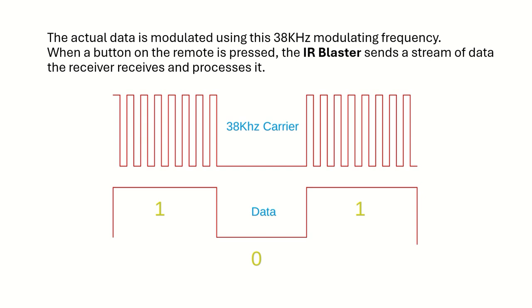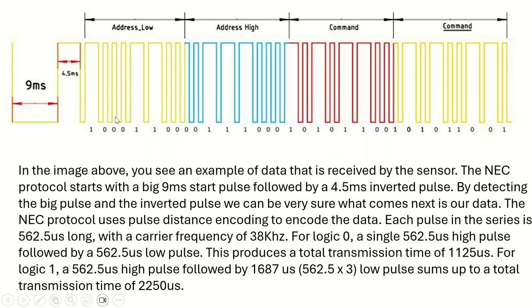So like I was telling, what do you mean by carrier frequency? Carrier frequency means whenever you are sending a logical one, it is nothing but a bunch of pulses. So this logical one consists of, let's say, 38 kilohertz burst pulses, which represent logical one or logical zero. They are using a high frequency so that it won't be visible. Right?